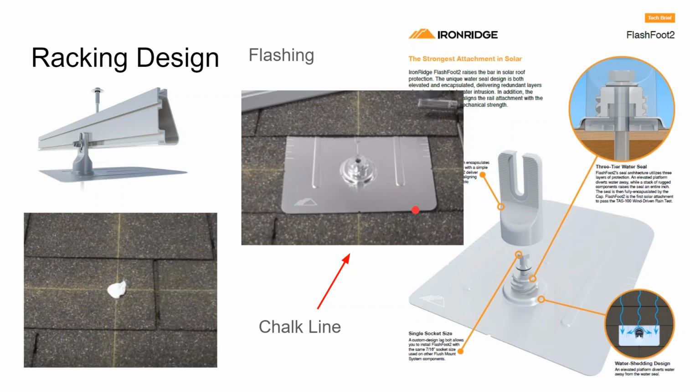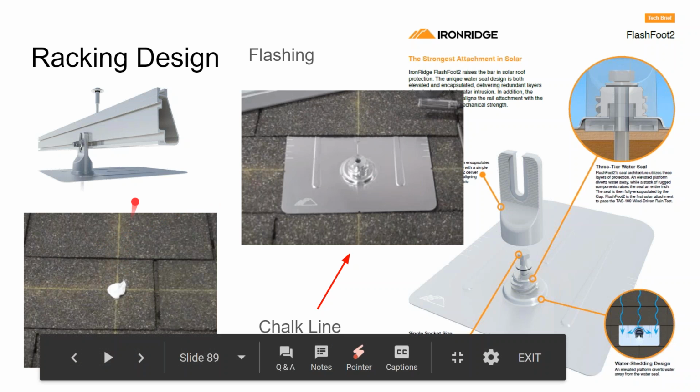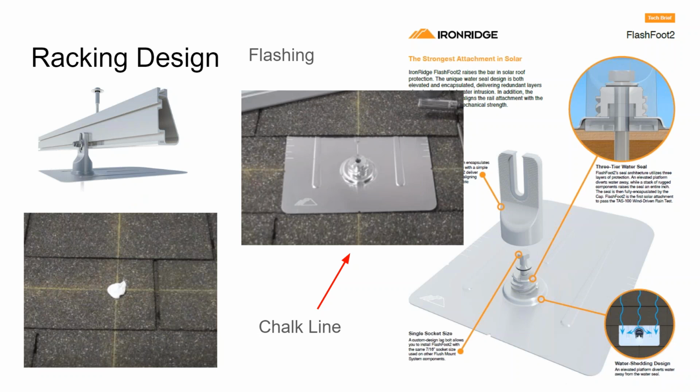Kind of the way the installation process works is you get up on the roof and either use a $600 stud finder, not a $50 stud finder, but a $600 stud finder, which is still tricky. You've got to get a flat piece of cardboard and use your stud finder through the cardboard and then through the roof, rather than on the textured surface of the roof. Kind of the old-fashioned way is to take a rubber mallet and bang the roof and feel where the rafters are, with the aid of someone inside the attic measuring it out.